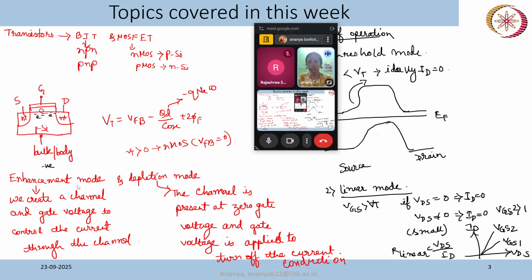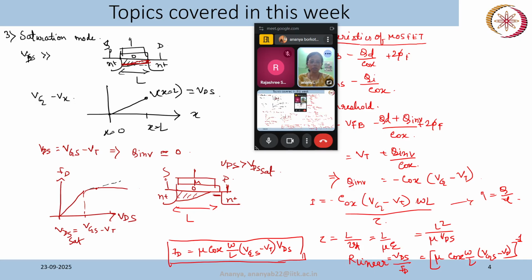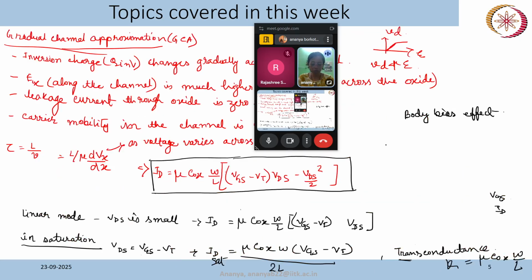We are basically repelling the electrons from this side towards this side. So we are helping in creating the channel if we apply a negative voltage to the body terminal, right? So our effective threshold voltage will actually decrease. So how much decrease? After the derivation it comes like this.